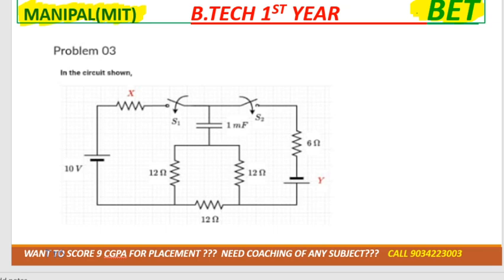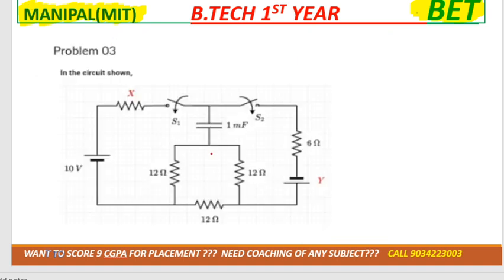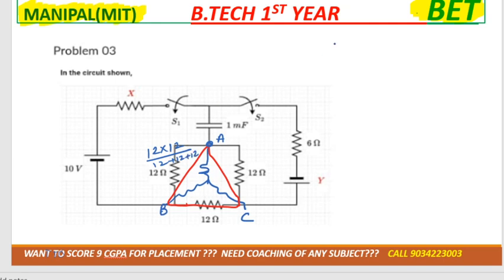Now see, this is the circuit. First we need to simplify these kinds of circuits, as we have done in this case, where the current source must be converted into a voltage source. Now as you can see, this is like a delta, right? So by simplifying it, we can convert delta into star. As I told you, the point is the same if it is connected to A, B and C, so how much will this value be? That is 12 into 12 divided by 12 plus 12 plus 12, right? So how much is this value coming after converting?